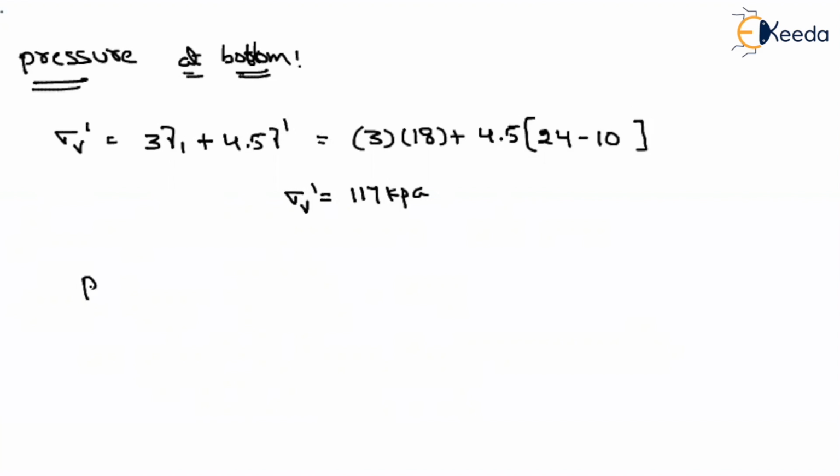What is the active earth pressure? That will be equal to active earth pressure coefficient Ka2 into vertical stress. So this is because of the soil, but again we are having some water. Because of the water, what is the pressure? Sorry, if it is water, whatever the direction, your pressure is constant, that's why it will be gamma W. Up to how much height is water there? 4.5.